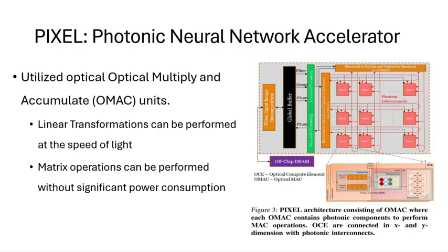Optical electrical circuits are capable of reducing the multiply accumulate operation down to a bitwise AND, which is then followed by shift accumulate. And for an all optical multiply accumulate, if we ensure the path length connecting one Mach-Zehnder interferometer's output to the next Mach-Zehnder interferometer's input is equal to the bit transmission period, 2 bits can be combined at the output. Over on the right is the pixel architecture of these optical multiply and accumulate units.